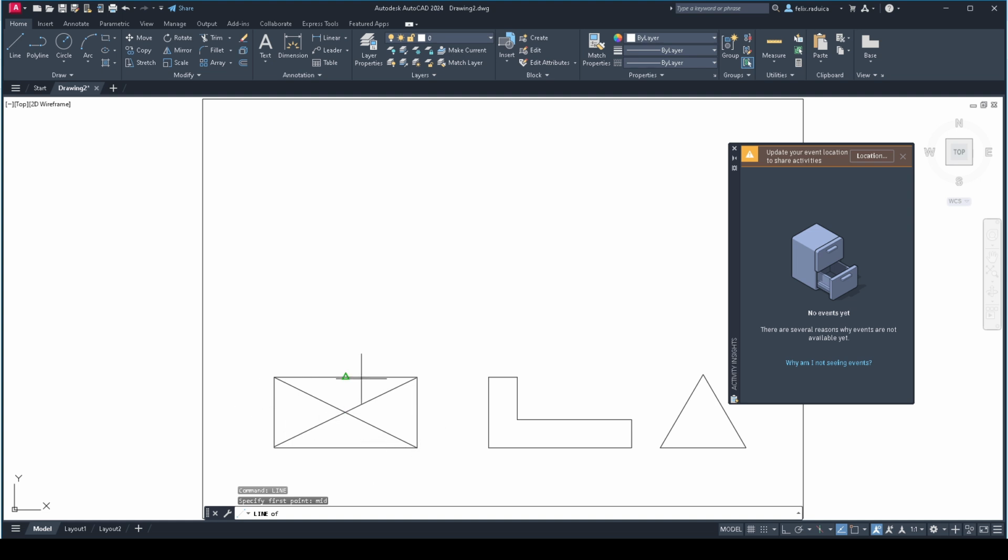So I can click here, for example. Now, if I want to snap to the end of this line here, I have to type in the end command. And now it snaps to the ends of the lines. And click. And enter. So now I'm certain that this is in the middle and it snapped, and this is in the end point and it also snapped.